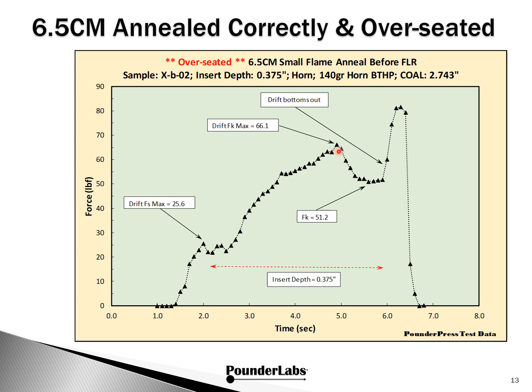But what you'll also notice now is a drop down to the kinetic force of friction. So the bearing of the bullet is well past the neck and just sliding further into the case. And you can see, instead of normally seeing about 300 thousandths, we've had an insert depth of 375 thousandths. You're normally not going to see this, but we just wanted to make up a case here to show folks so they'll understand where that measurement comes in.